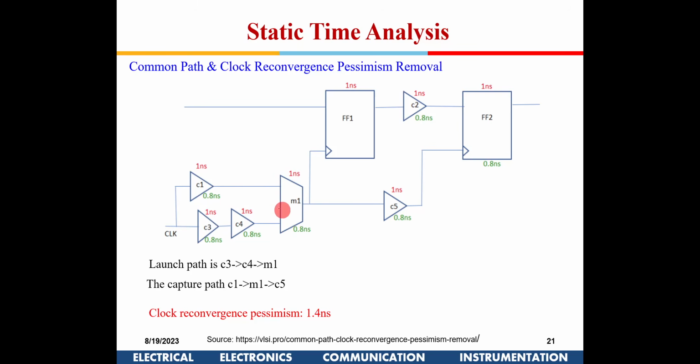The mux would select either this path or this path, probably for day operations and night operations. This is just a random example. So there could be multiple clock paths selected through a mux, and that mux is controlled by signals which are not purely dynamic in nature. That could be based on other environmental conditions or operating conditions.